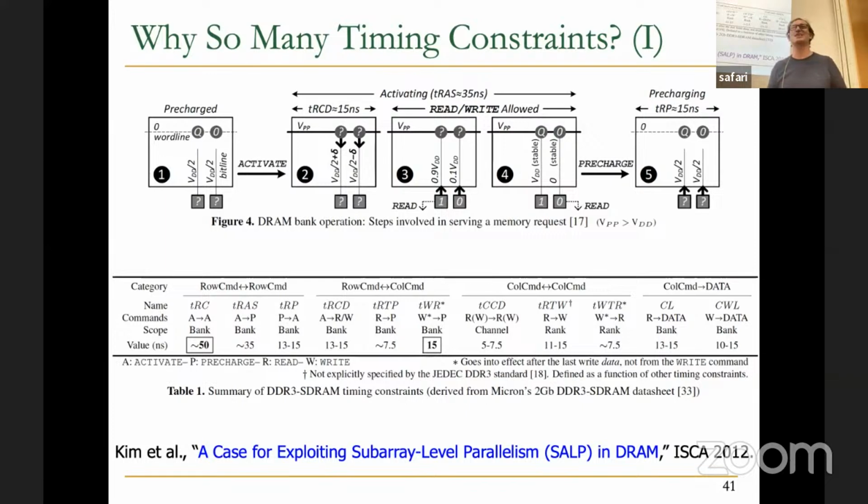No, it doesn't exist. The assumption is that it's completely reliable. Yeah, but in really extreme scenarios, there's an alert signal that could be raised by a DRAM chip that says something wrong has happened with me. Exactly, for writes you don't necessarily know. There's no acknowledgement. We're going to talk about some of that soon. So the assumption is that basically the memory handles all of that and it doesn't need to acknowledge. This also reduces the protocol overhead in a sense. If there were acknowledgements that you need to wait for, the protocol overhead would be high. And acknowledgements are useful in unreliable medium, of course. The assumption here is it's reliable mostly, hopefully. So you can see that it's not designed for complete robustness.